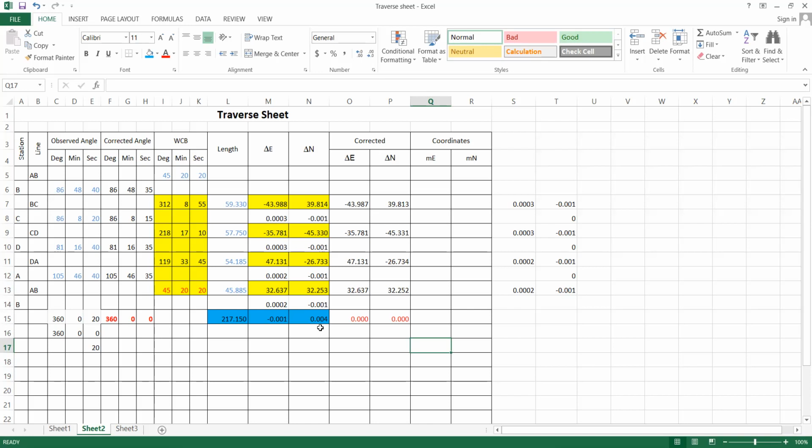If you have a large error, then you have significant amount of corrections. For example, in this case, if you have, let's say, a 20 millimeter error, right? If this is 20, then you will have some larger corrections. In this case, actually, it is just 1 millimeter. Then you cannot distribute it proportionally to the accuracy of third decimal. If you go for smaller decimals, it is not necessary. As we have measured all the lengths up to 1 millimeter, corrections up to 1 millimeter is enough.